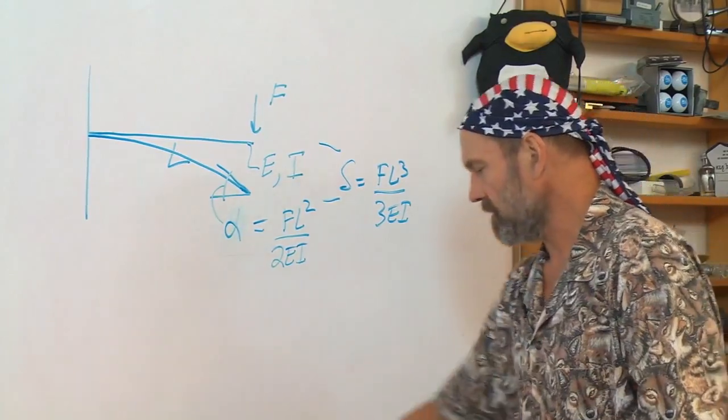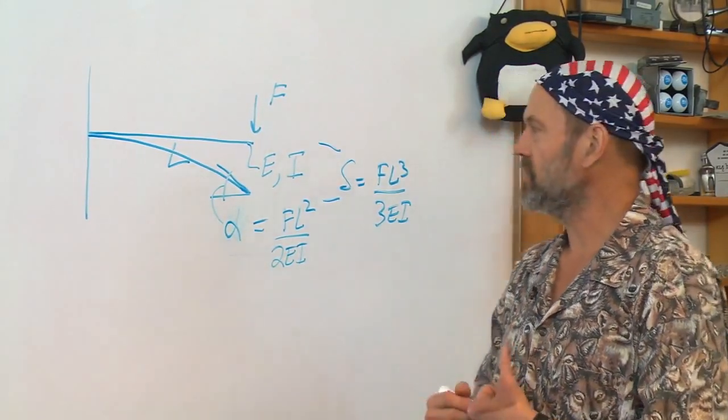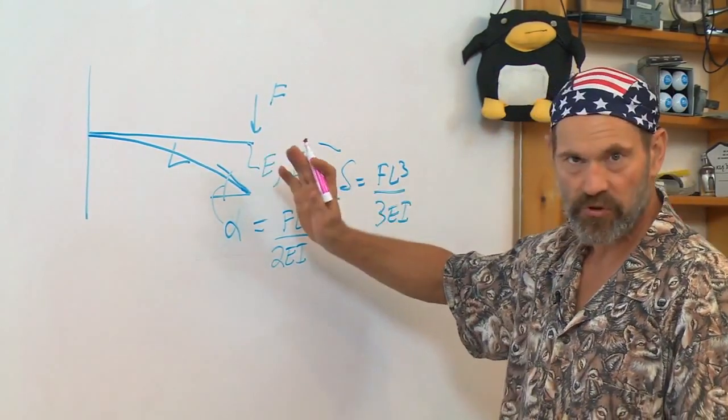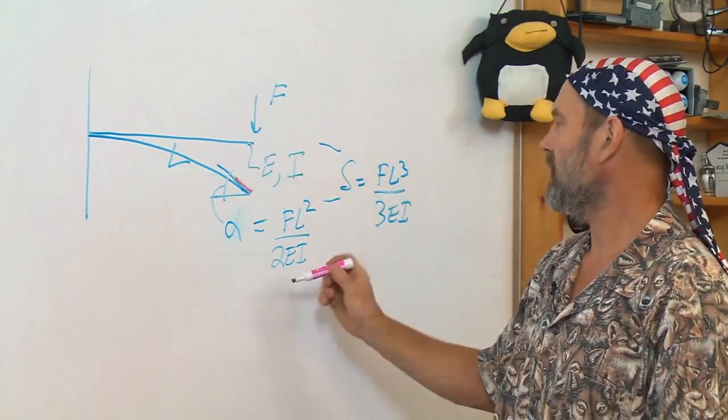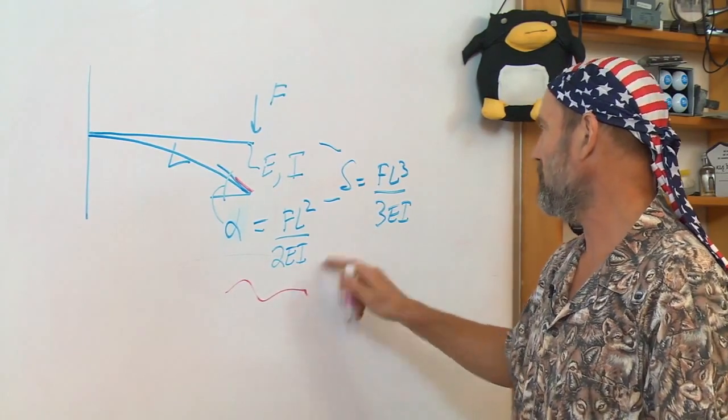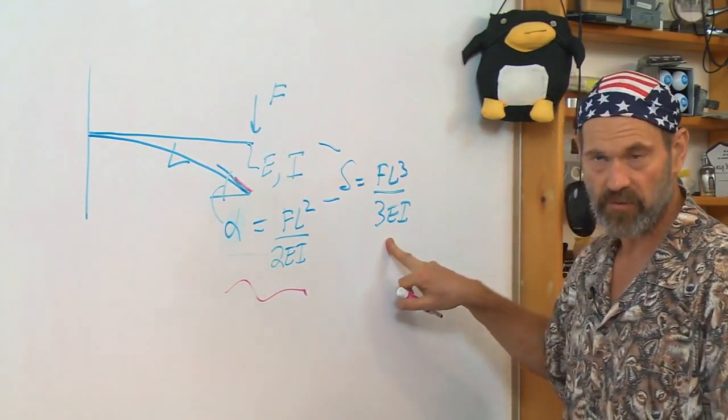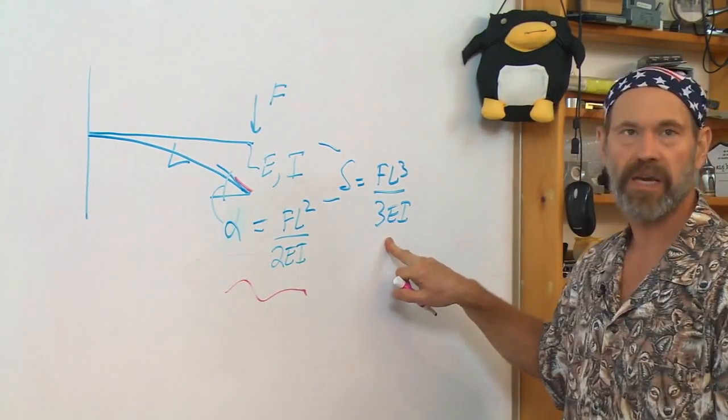So if you were to mount the lens element you're trying to create with pure rotation at the tip of the beam, you would get, for example, the slope you want, but you'd also get this deflection, which from the function required would be a parasitic motion.